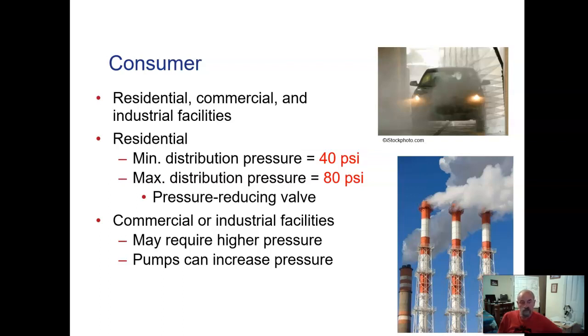For residential consumers, like I said, 40 psi is a minimum, and a pressure over 60 is considered high. Because it increases the flow rate, high water pressure can lead to increased water use or waste and increased energy use due to the heating of the excess water. In addition, high water pressure can damage appliances too.